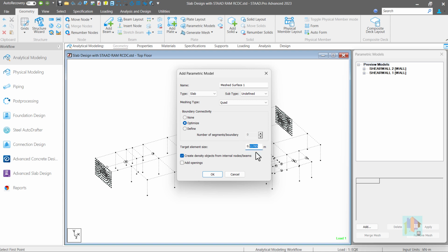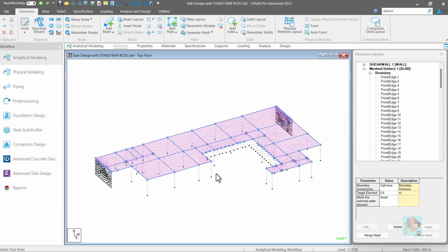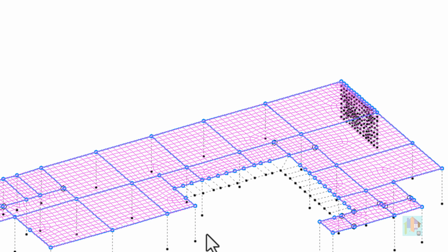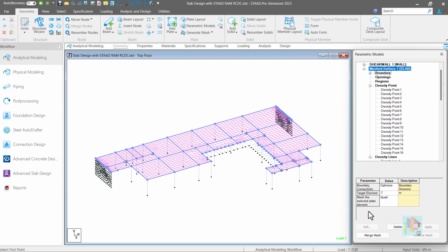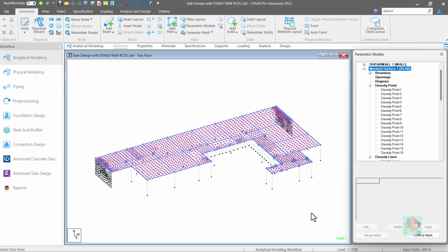During mesh generation, program considers all internal elements and creates the boundary nodes properly, considering existing plate or member. As you can notice, all members, nodes, shear wall plates are considered in this mesh. There is no plate or beam connectivity problem. We can further customize the mesh size, make it coarser or finer, add opening for stair or lift, then finalize this mesh. Using this method, we can model an accurate geometry of the slab with correct boundary profile and opening.